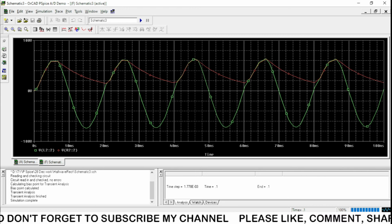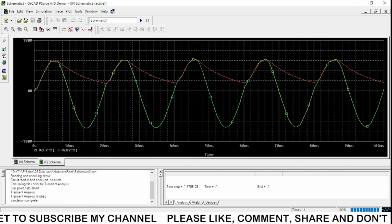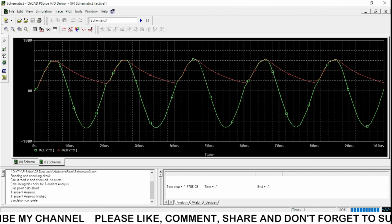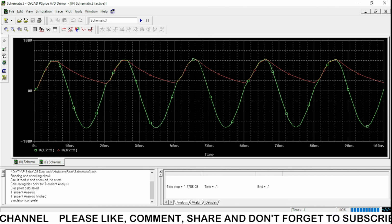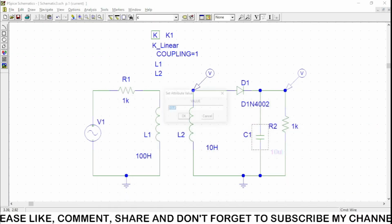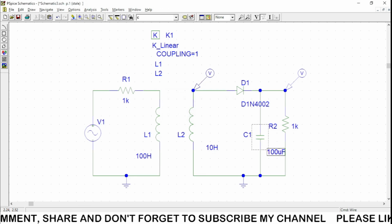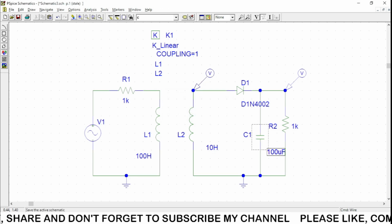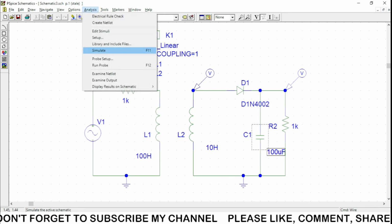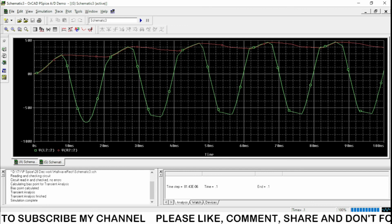If we take the very small voltage of the filter, you can see that it is charged for this positive part, it is discharged like this, it is charged, it is discharged like this, and so on. So for that purpose we need to understand that the value of this capacitor should be not very large and not very small. I am sticking with the 100 microfarad capacitor. I'm going to simulate it, and then I'm going to get the graph like this.